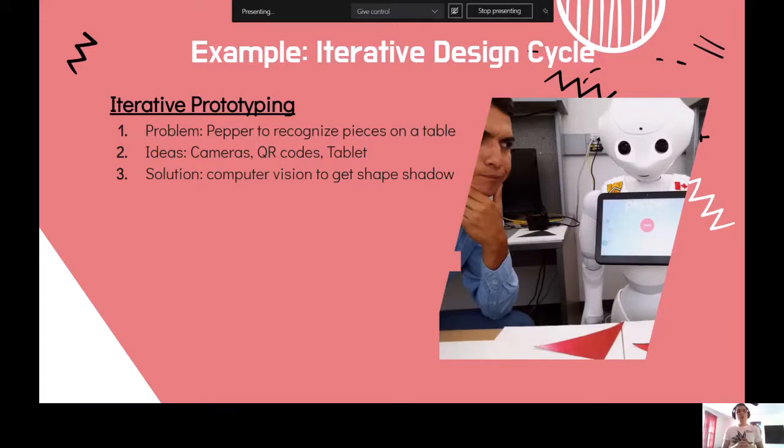We took one of the solutions and we started seeing how to use the different cameras of Pepper to basically get the shape, the shadow with the specific shape that we were arranging when playing the tangram. So we used the camera that Pepper has in the mouth to avoid Pepper turning down his head and avoiding that important eye contact when interacting with robots. We noticed that some of the risks associated to this solution is the puzzle orientation. Every time we had a different orientation of the puzzle, Pepper was detecting something totally different. So we were detecting a different area, or a different percentage that was not necessarily what we wanted at that time.